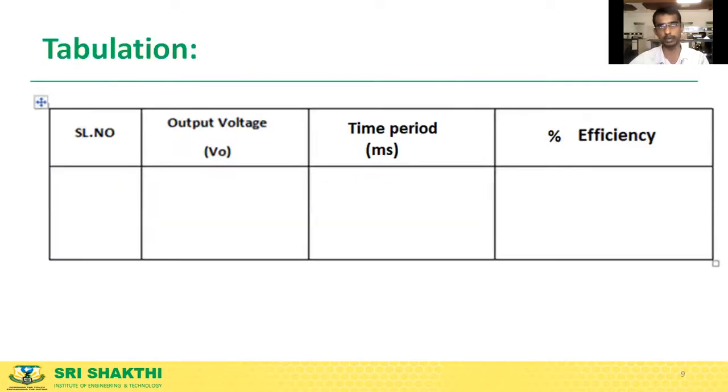We don't vary the frequency. It's not a frequency response. We're directly going into measuring the efficiency. For example, in Class A, in the last experiment, we got efficiency around 9%, and theoretically it is around 25%. We are going to see what happens today.